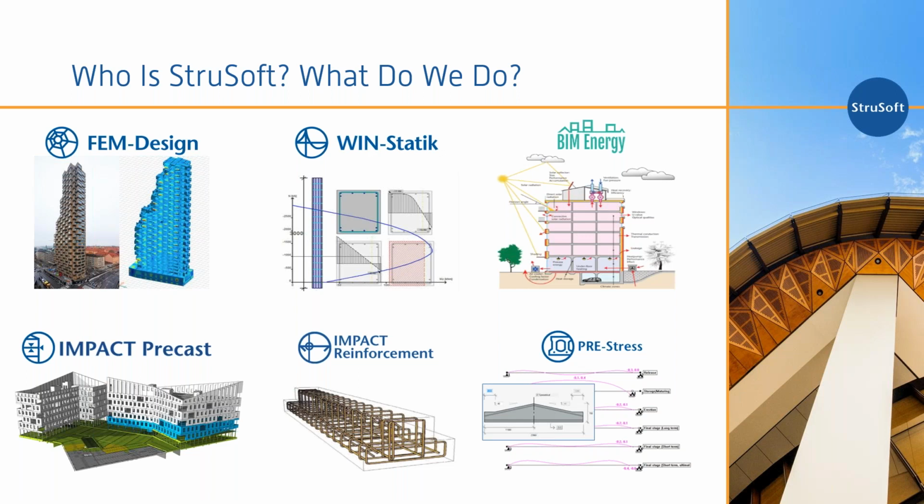WinStatic is a smaller program which deals with individual element calculation and design. And I mean beams, columns, frames as a whole. And you can calculate and design concrete and steel elements.